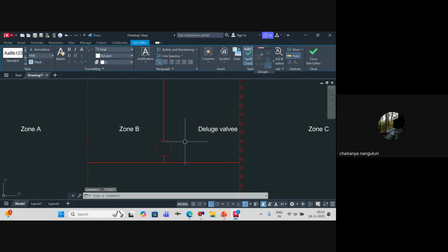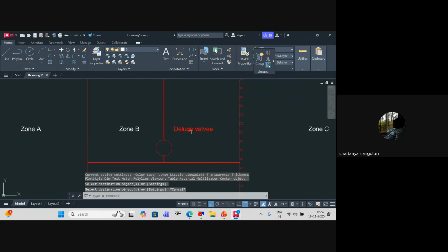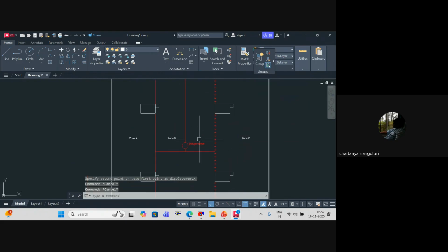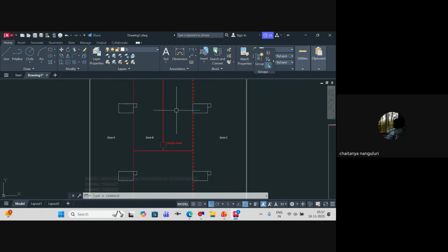So when we have this deluge valve, what we do is simple. The minute we have this deluge, if I do it in the corner, your pipe sizing will be different. That's the reason. But when you have this deluge valve, the first and foremost thing to understand is, up to the deluge valve, you can use your MS pipe. But after the deluge valve in the water flow, you have to use GI or SS. GI is 99.99% what we use because of the cost.